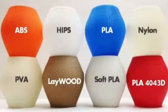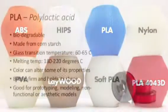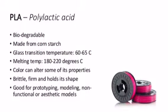The material used with this type of 3D printing is called filament, and there are many different types. Polylactic acid filament, usually referred to as PLA, is recommended for use in public libraries since it is biodegradable and does not emit an odor while printing. PLA also melts at a lower temperature than some other filaments, so it is a safer option. PLA is also a generally easier filament to work with.